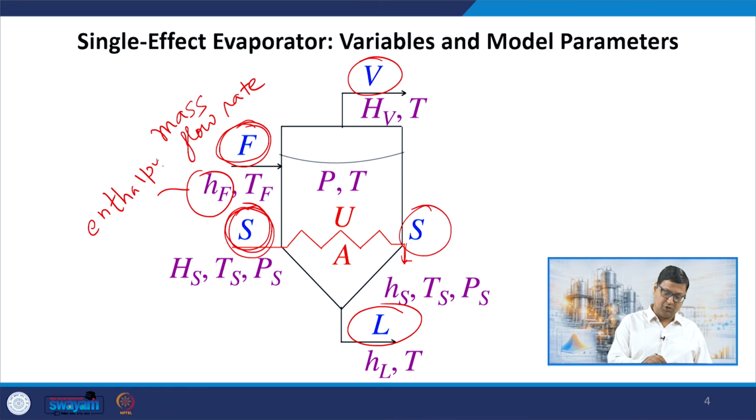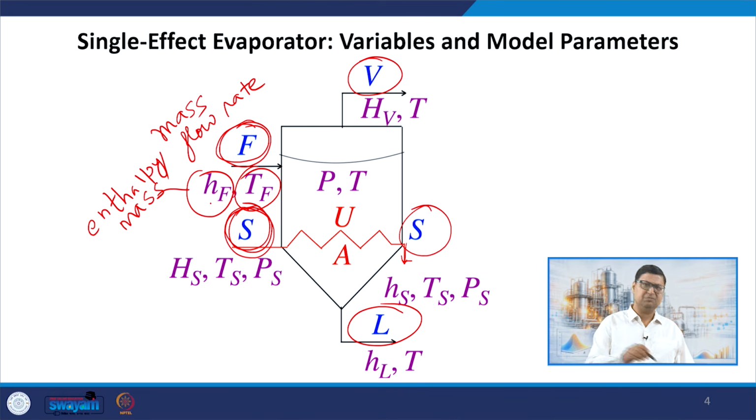Again, we were using molar enthalpies earlier, but now we are talking about enthalpy per unit mass because it's a single component solvent and only one solute. And this enthalpy corresponds to some temperature Tf of the feed. Now, the steam also carries some enthalpy Hs.